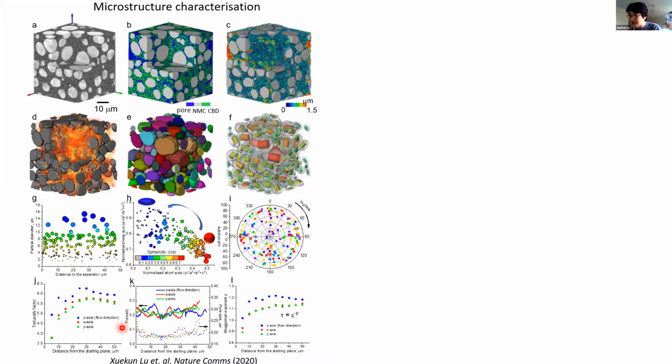Here we can also analyze the porosity and the pore size distribution in 3 orthogonal planes. We notice a large fluctuation of the porosity and also the pore size. This indicates the microstructure is not homogeneous. And this figure correlates the tortuosity as a function of the porosity.